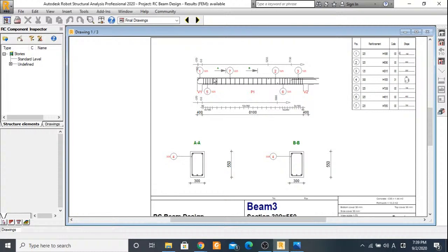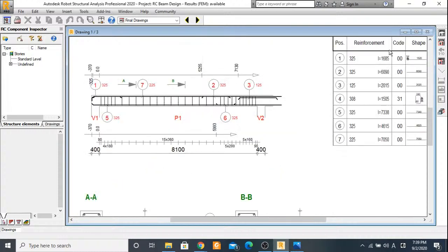If I cut here, there should be two bars, I'm sure. All right, so we have 3 bars of 25 down this way, and then we have our shear links this way, 4 of them spaced at 180, and it goes on and on.